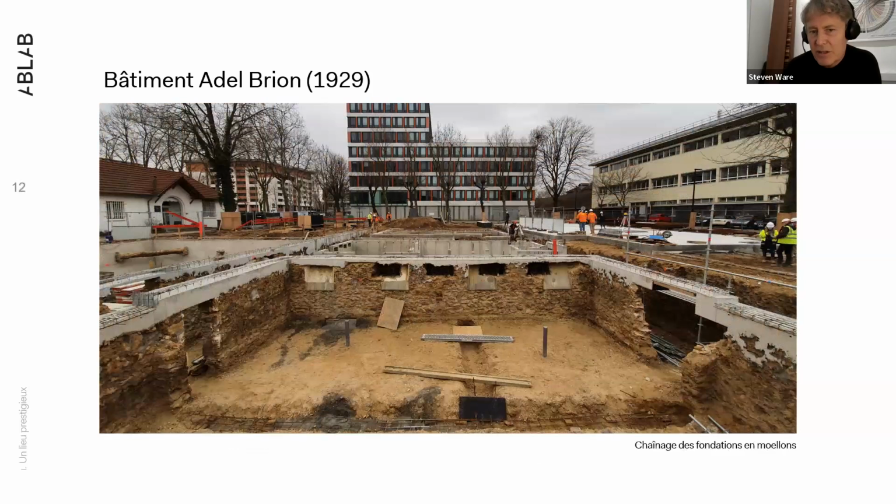That's an idea of what the foundation started to look like. So we've got this fieldstone foundation, which is actually very, very weak. But with a little bit of concrete poured on the tops, we were able to pretty much sit the new building on top of those existing foundations, with one or two exceptions. But I think that's something which is also extremely unusual these days, given that what tips you over in the bad way in terms of the carbon analysis of an ordinary building is mostly the work that you're doing below ground. A lot of concrete, a lot of digging, a lot of energy. Here we were able to really minimize the amount of work that went below ground, below grade.